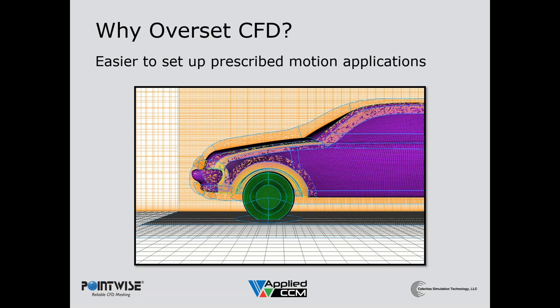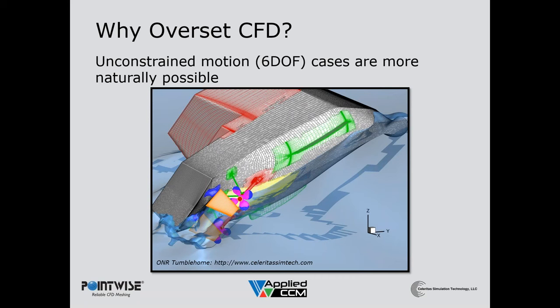Maybe another typical approach for doing rotating is that you have one region moving, the other region static, you have some interface grid, and that interface grid necessarily needs to be cylindrical. But in the case of this wheel, it might be very difficult to stick in a cylindrical set of patches to facilitate that interface. And that's not necessarily the case with Overset. So you can overcome some of these traditional difficulties. Okay, next one.